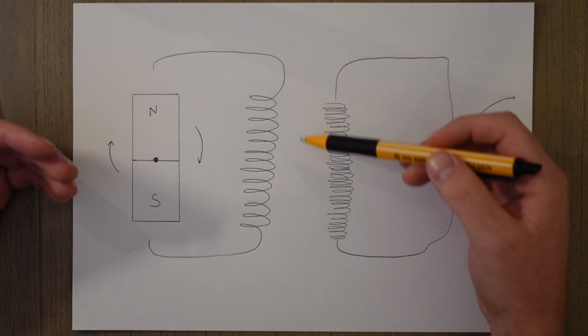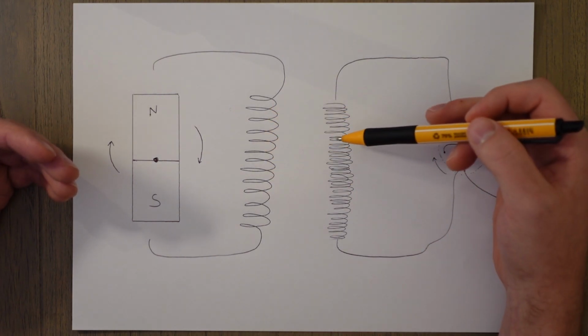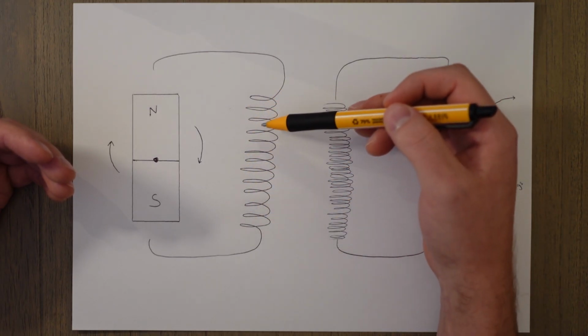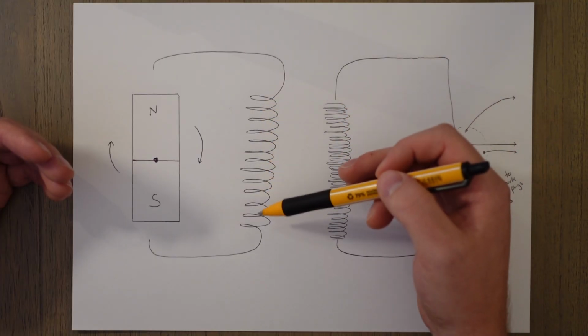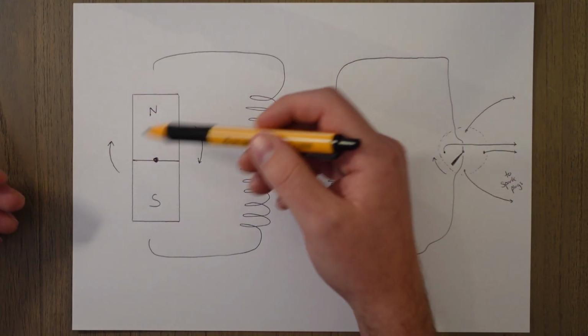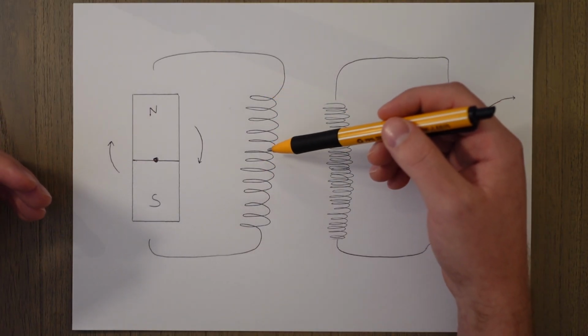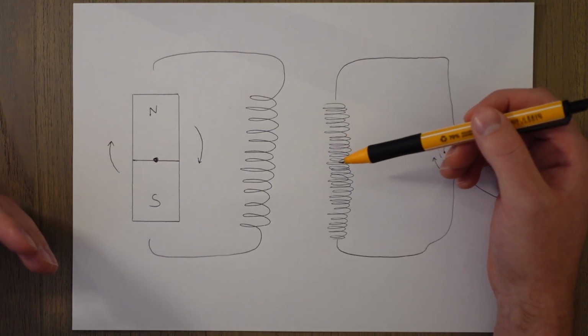If we have an AC current flowing through a wire and we place it next to another coil of wire that is separate, then as the current flows along the wire, it creates a magnetic field which is constantly pulsing and switching directions along with the magnet that is generating the electricity in the first place. This magnetic field influences the electrons in the unconnected wire, therefore causing a current to flow in that wire.